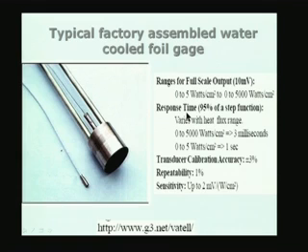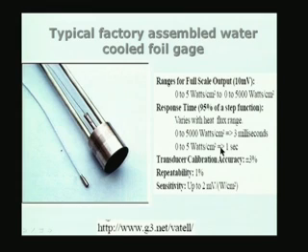Response time, which is what we talked about just a little while ago: you can have 0 to 5000 watts per square centimeter, which has a response time of 3 milliseconds. The 0 to 5 watts per centimeter square case requires 1 second. Why? Because you require a large radius, otherwise you are not going to get enough delta T. When the heat flux is large, the delta T is going to be proportional to that, and therefore you get a large enough measurable delta T with a small radius, whereas with very low heat flux, you require a larger catchment.